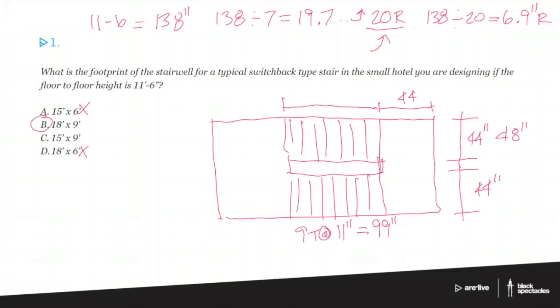Now, interestingly, if you actually look at the treads, the classic accessible stair is going to look something like that. Not very well drawn, but you get the idea. So there's the 11 inches, but typically I actually get another little inch or so back underneath there. So the actual tread dimension is usually about 12 inches, but if you're looking at it from a plan standpoint, it's 11 inches clear because that other little angle gives you just a little bit more space for the toes.